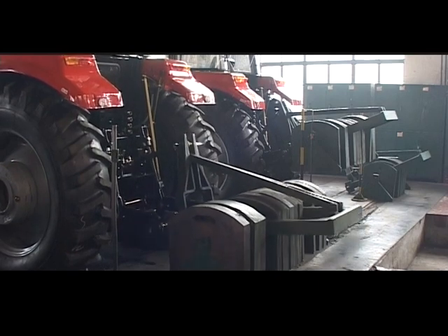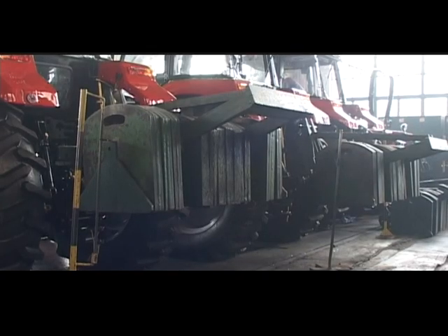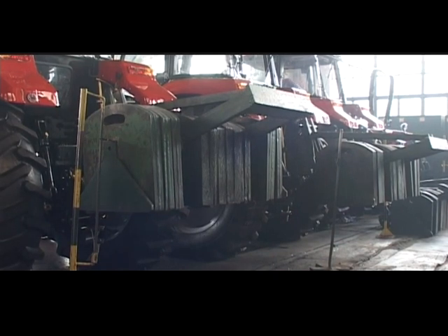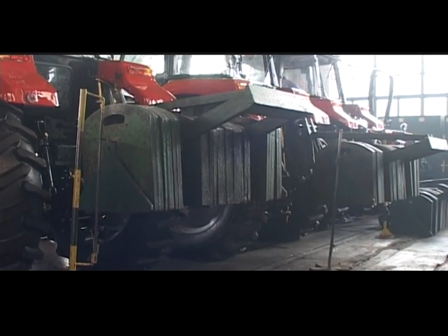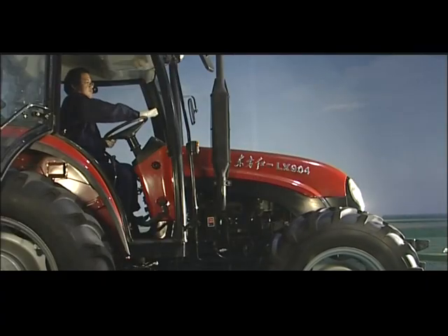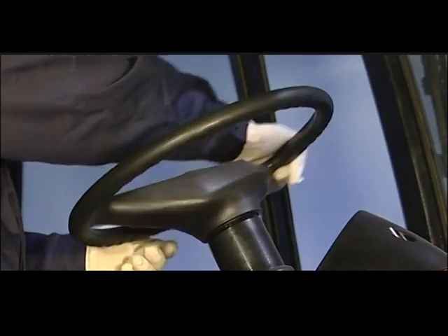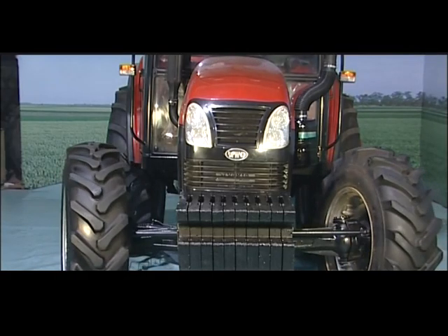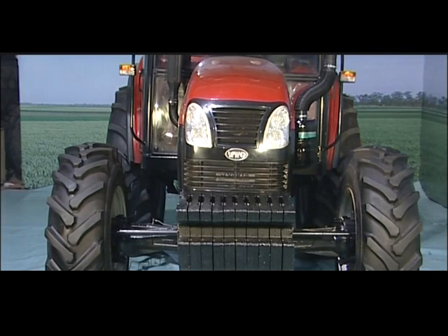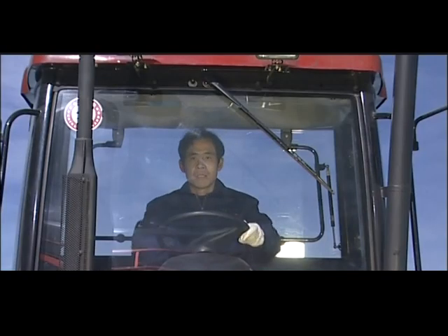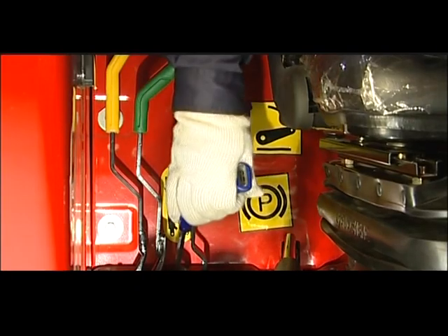Observe if the hydraulic hitch device can be fixed at highest or desired position, and check if there is oil leakage. Under the normal condition, when the tractor is still, run the engine at low, mid, and high speeds. Steadily operate the steering wheel left and right for 10 times respectively. Observe the movement of tractor front wheel during left and right steering. Listen if the noise is normal, and check if the steering wheel operation is steady and easy.